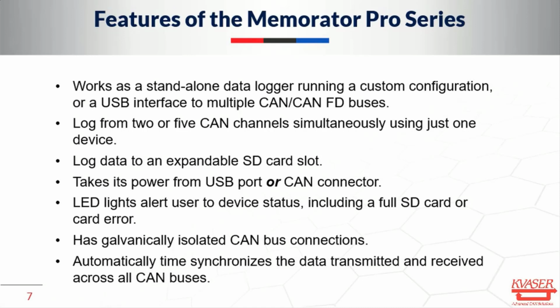They do have LED lights that indicate the device status, including an SD card full or an error, and the LED lights will indicate that it's connected through USB to a PC as well. Galvanic isolation between the USB port and all of the CAN channels. It also automatically time synchronizes the data transmitted and received across all CAN buses. Their internal clock will time synchronize all of the data that it logs with an accurate timestamp.